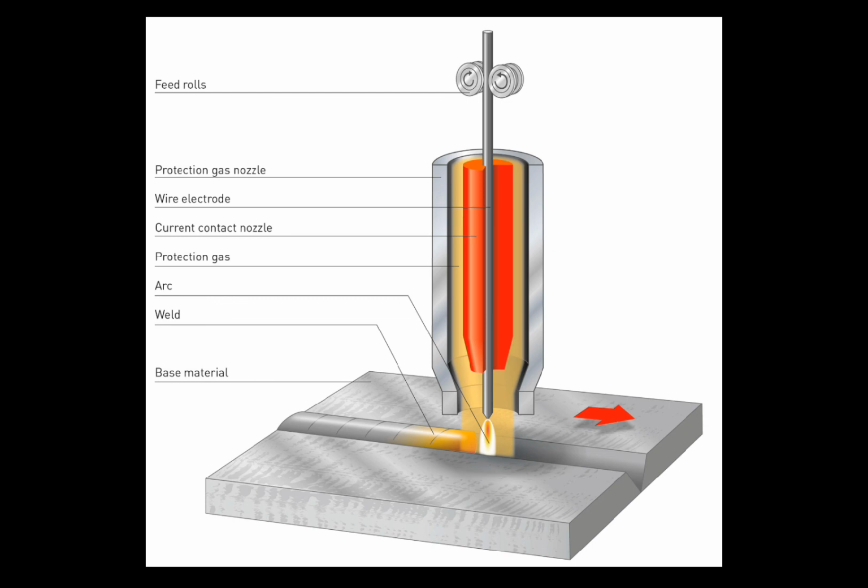Why must all flux be removed from the metal after welding magnesium? Can result in severe corrosion if any flux is left on the metal. What must be done to successfully weld titanium? Must be shielded with an inert gas, such as helium or argon.